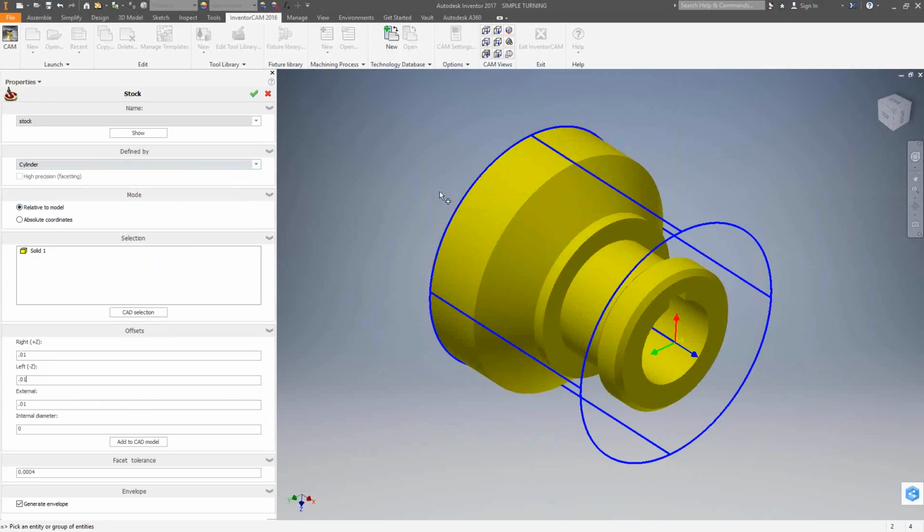And that is actually the major difference between turning and milling. I want to put some material on the faces and the OD so that InventorCAM recognizes that there is some additional material that can be removed by turning operations. If I don't have any material there to remove in this simulation, then it won't generate the toolpath because there is no material to be removed as far as it can tell. So that's really why I'm just putting that 10 thou there. You can consider this to be something just to true up the part, even if it is almost on size.